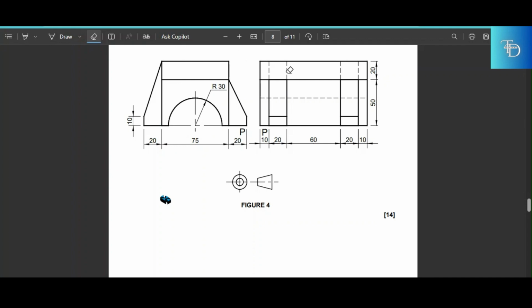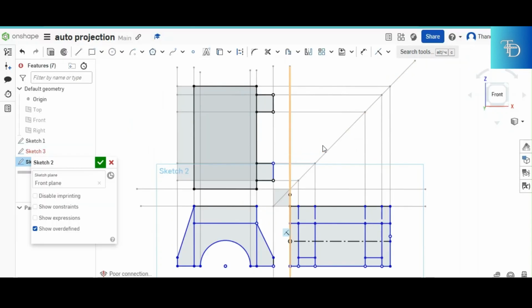Hence the hidden details. That is why these hidden details are continuing exactly from these right hand side webs to the top side. The reason why they're continuing and equal to this, the thickness is equal to these right hand side webs, is because they are telling you that since these webs on the right hand side are 20 millimeters thick, same thing applies for the ones at the opposite. They are also 20 millimeters thick, but the height goes all the way up to the top of the component. So coming back to your answer sheet, you do the same thing.